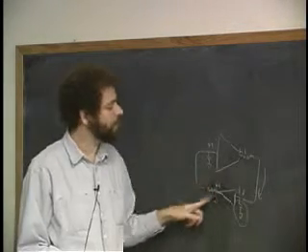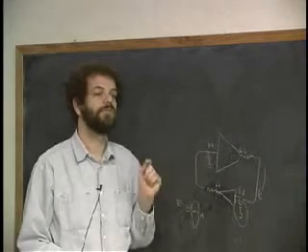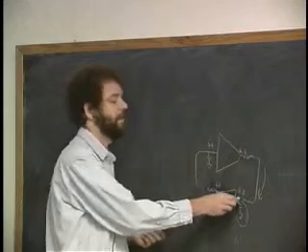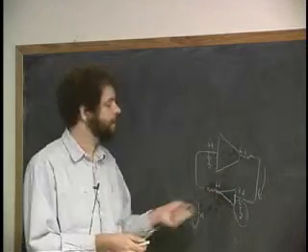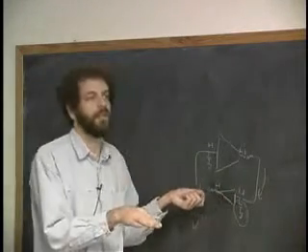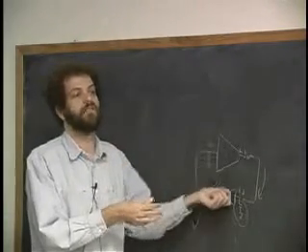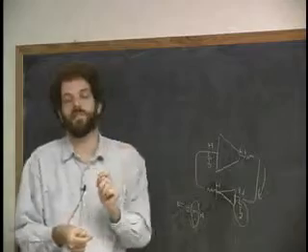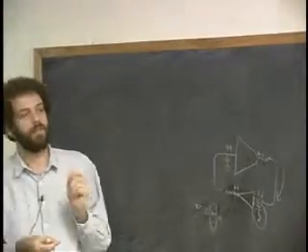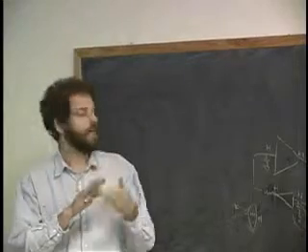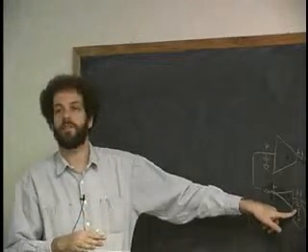And what these circuits are doing is nothing more than refreshing that bit. They're constantly reading the bit, seeing if it's a high or a low. And if it's a high, even if it degrades a little bit, it restores it with a high that is of better quality than what it read. Exactly the same lesson as when we talked about how dynamic random access memory worked. Do you remember? That was a matrix of little caps just like this one here.